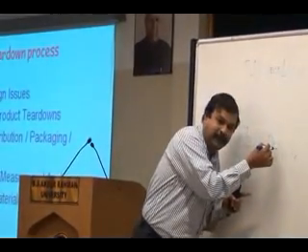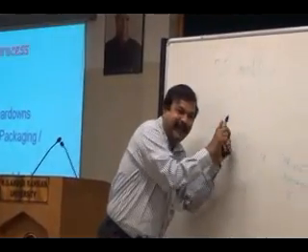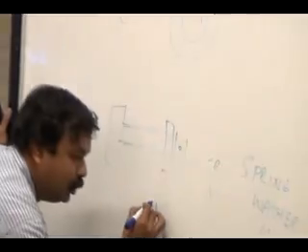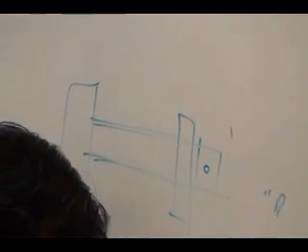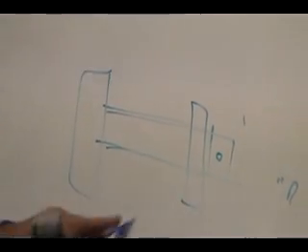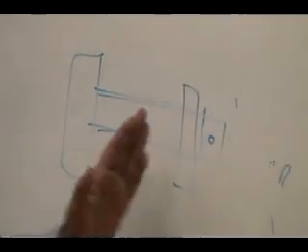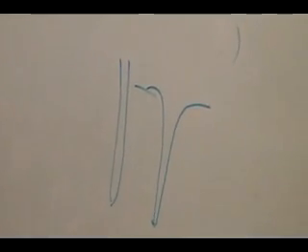So you insert a hairpin, and then the free ends are opened out. In the unopened position, it will be like this. After it is opened, it will be something like this. This is open, so this cannot come out. So even if the nut is loosened, it cannot travel beyond this particular point. This is called a split pin.